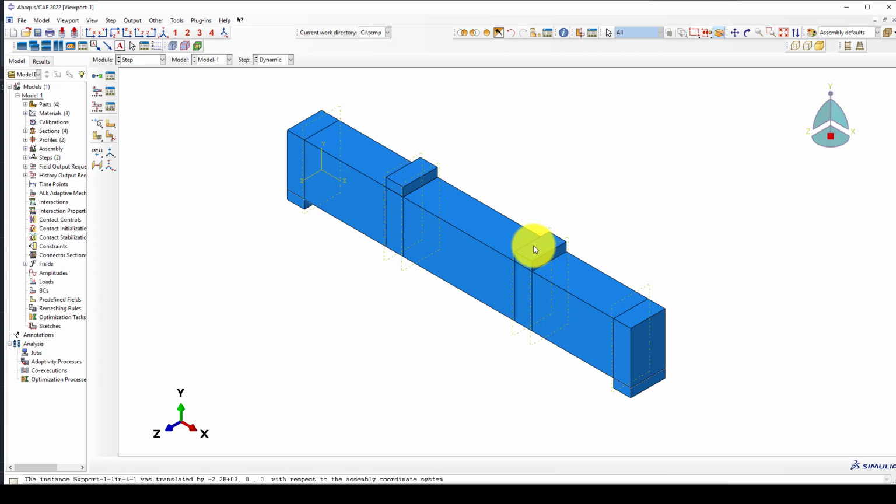At the same time, we want to apply displacement instead of load, at the same points, which will give us force and displacement. Then the average of the displacement, we will take the maximum displacement, and also the sum of that force equals the capacity of this beam.